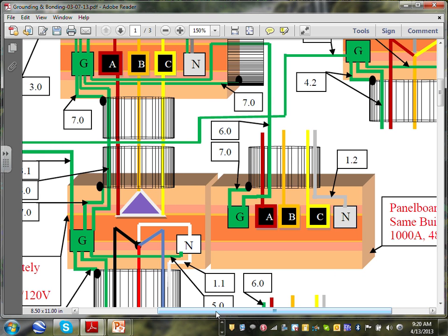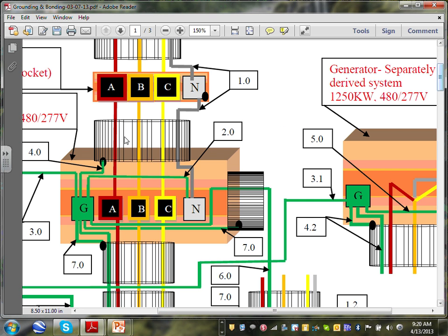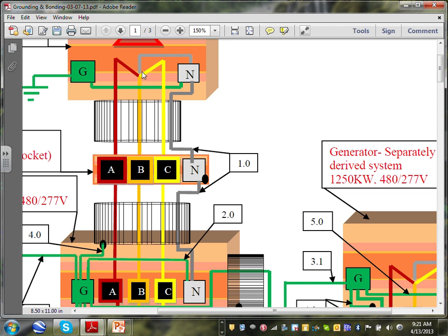While here, guys, if you have a short circuit in that conduit, look at this. If I have a short circuit in that conduit, the short circuit is going to go right through that number 4 into my grounding electrode system, or see in the panel, and it's going to go right through the conduit back to the source, back to the source of the short circuit. So either way, where's my overcurrent protection device in this area? None. There's no overcurrent protection device. I'll show you when we do arc flash. I'll show a couple of arc flash examples later on in the afternoon.